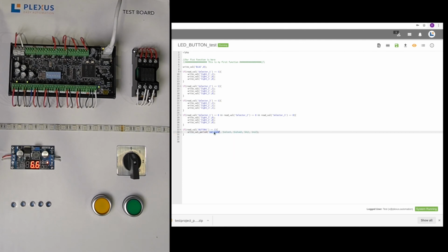period red, and it's going to tell us what the first value should be. So we want to trigger between 0 and 1 at a speed of, let's say, 200 milliseconds for 0 and 400 milliseconds for 1. This little block here says that the red LED strip should be 0 for 200 milliseconds, then 1 for 400 milliseconds, and it will keep looping like that.